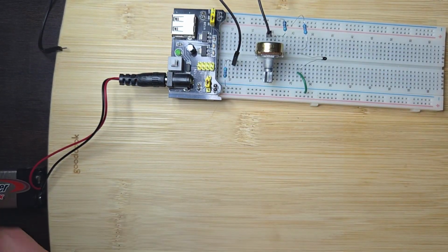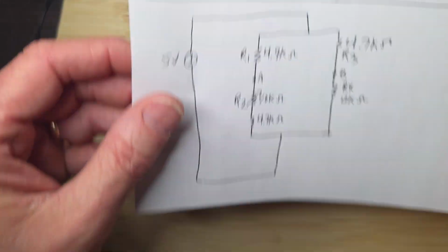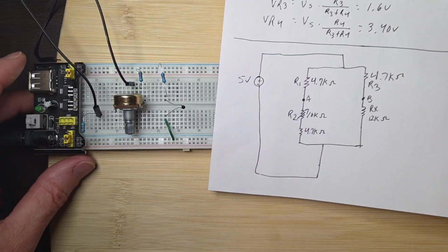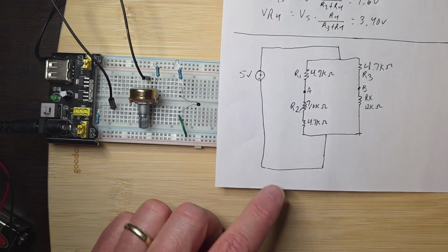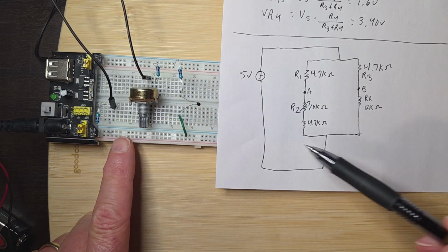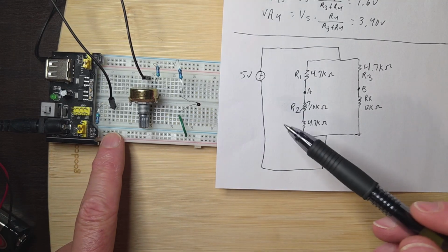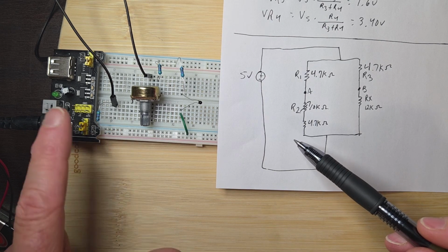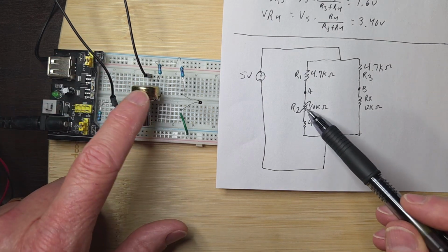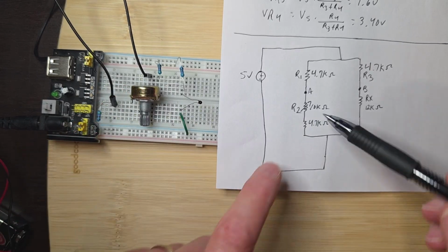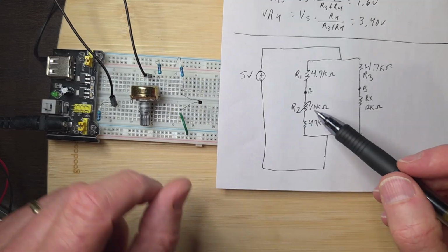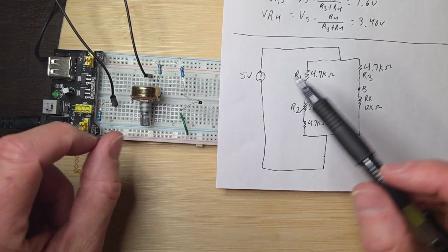And so ultimately, what I just did was, and I'll put this to the side and show you. We're at ground here, on the negative side of the battery. I took that little 4.7K ohm resistor and wired it in series with this variable resistor. So now that's like 14.7K ohm variable. Well, 10K of it's variable, but it's enough to match this guy.